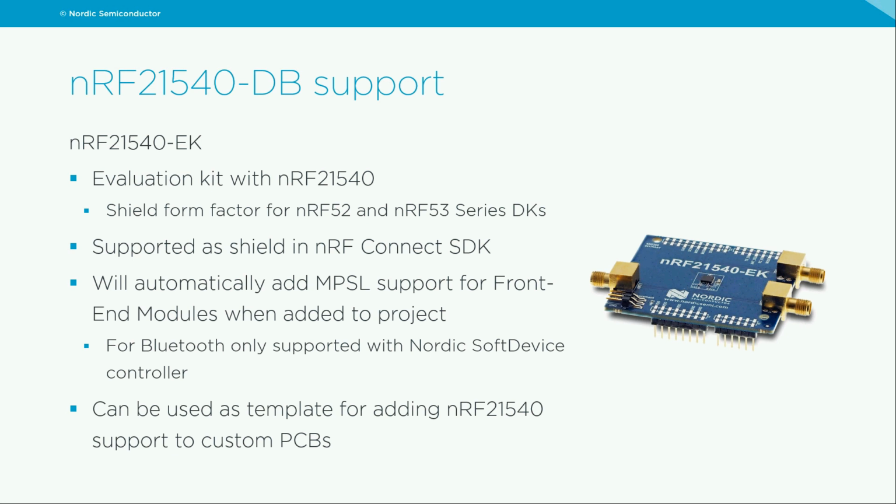This means that if you have a project which you build for an nRF52 DK or nRF53 DK, you can say that you want to add the shield. As soon as you add the shield to your project, we will configure it to use MPSL, so you get the front-end module support in. There will be an overlay file that comes with the pin configurations and everything you need to set up to make it work. And because of this, adding the shield to another DK is fairly easy to do.